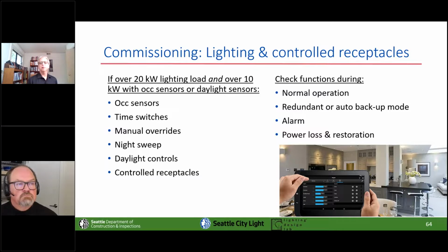I have panels up on my roof, and its whole maintenance routine is that once a year I get up there and stand and say, wow, that's a really cool solar array. And maybe I swab it off if there's some dust on it, maybe not. Whereas solar water heating systems require maintenance, and they have moving parts, and there's potential for leaks, and there are other things that conspire to make their lifespan not that long.